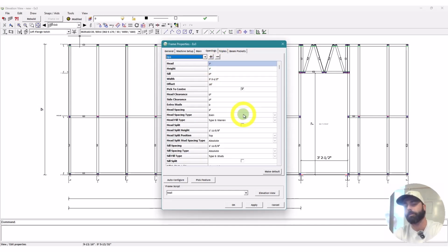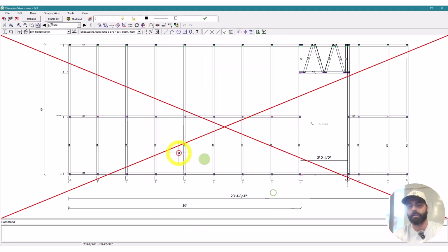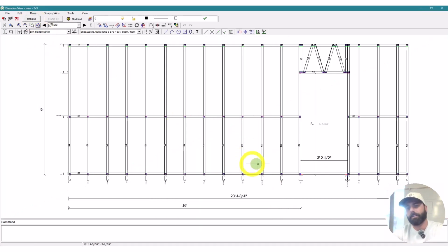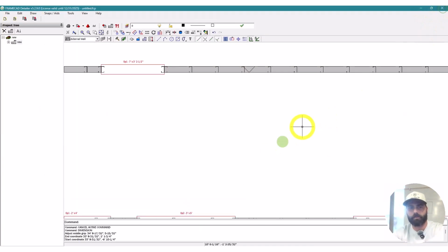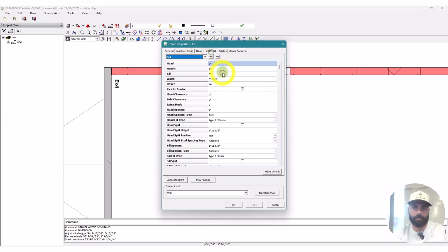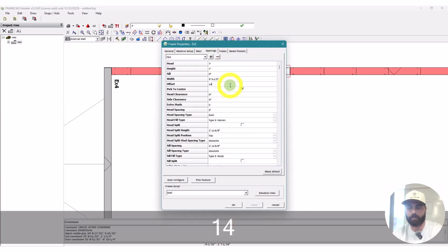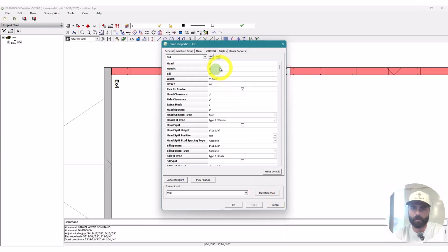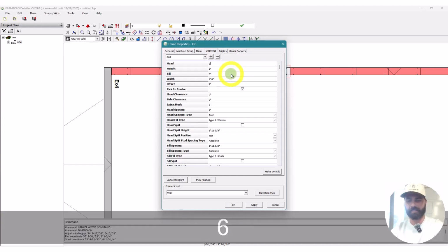We'll go ahead and do this. We'll pull that back a little bit. And do 14 feet. And then we get to watch the video and then duplicate. Well, I wish we were doing a prettier one than that. This one will be 6 feet, now we'll do 7 feet. 3 feet. Width, we'll do a 5-foot opening again, and we'll offset that 8 feet into the tiny house.